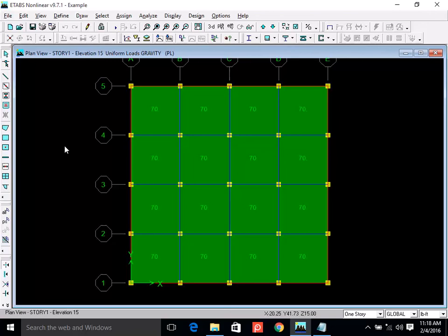It's because you have defined them separately. There is an option you can actually define only one dead load. I have defined 3 dead loads: partition, floor finishes, roofs separately. If you choose to define only one dead load, then you have to manually add them before applying it.